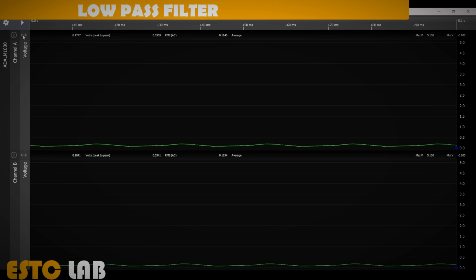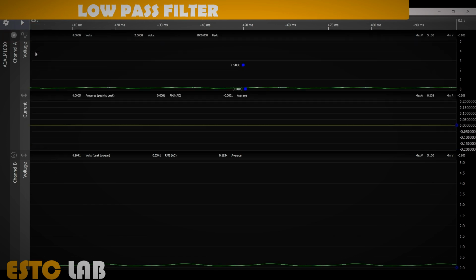For that, I click on this icon and change the voltage to sine and set the lower value to 0.5 and the higher value to 3.5. That means the lowest point of our sine curve is 0.5 volts and the highest point of our sine curve is 3.5 volts. And change this frequency to some 10 Hz.